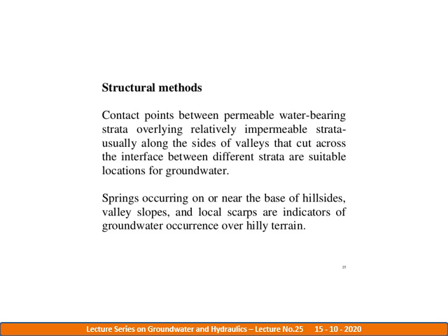In the seismic method, elastic waves are generated by a source of energy. These waves are reflected and refracted at the boundary planes between different soil and or rock layers. The travelling times of the waves are recorded by sets of geophones, which are located at increasing distances from the impact point. This method is not often used in groundwater prospecting due to the large capital investment and high running cost.